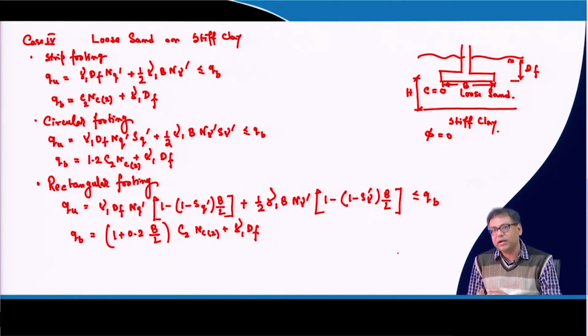So, there is a possibility that there may be local shear failures, but in the equation that I use during the bearing capacity calculation, I use all the cases. Even when I put the foundation directly on the loose sand or the weaker soil, I consider all the terms, the bearing capacity factors, that are proposed for general shear failure. That means I have used all the bearing capacity factors proposed for general shear failure, even though the soil is weak soil, and I put the foundation directly over there.